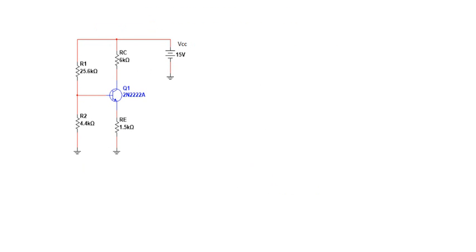That is VCE cutoff. And that's just simply the supply voltage. Because that's the voltage across the transistor, VCE, when IC is 0. If IC is 0, that means the current through RC and RE is 0, and Ohm's law says their voltage drops have to be 0. And so Kirchhoff's voltage law says all the supply voltage has to drop across the transistor, VCE.